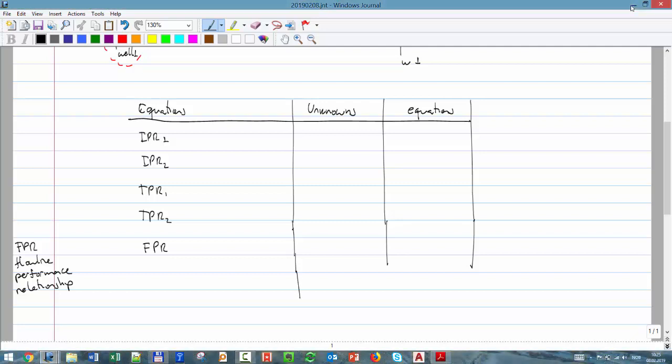And after that we have the equation for both chokes. The equation of the choke gives you the delta P across the choke as a function of the rate and the opening that I have on the choke. Let's call it CO, choke opening, and I have one equation for each.